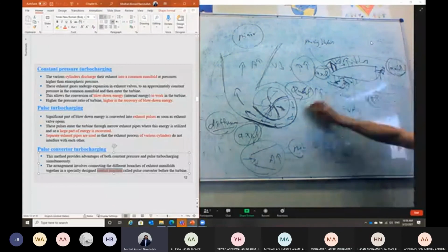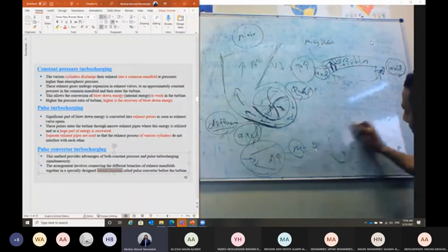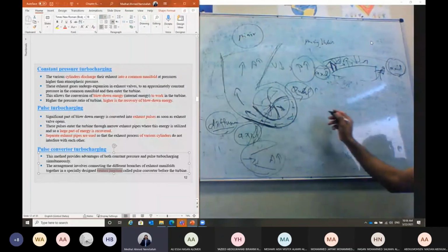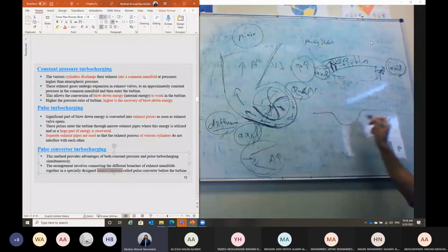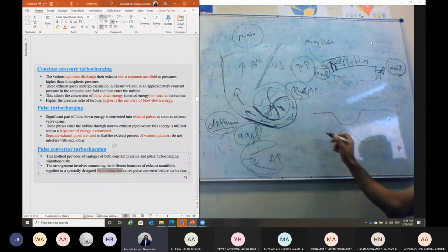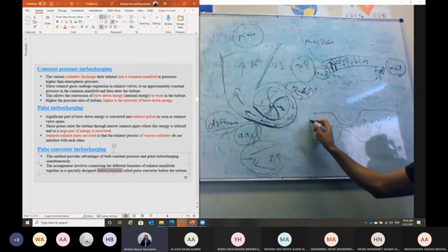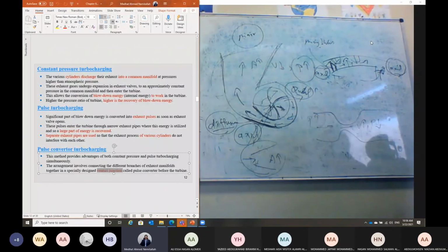And also we use a common exhaust gas manifold in this design for all of the cylinders before introducing the exhaust gas to the turbine. But in this case, we provide the design with a kind of Venturi. So when the common exhaust flow goes through this Venturi, the area is reduced, the velocity will be increased, and the pressure will be reduced. So the pulsating flow at higher pressure, when we pass it through this Venturi, will try to damp this pressure pulse.